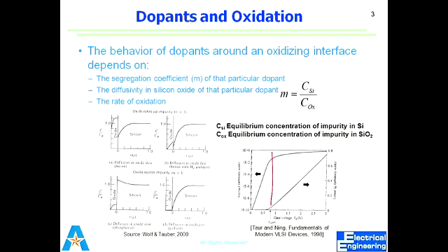As more and more oxide grows, it consumes a particular amount of silicon, because it's consuming silicon to grow the oxide layer. So a particular amount of silicon is consumed and a particular amount of oxide is added, and this is the total thickness now. So the silicon and silicon dioxide interface also changes, and the rate with which that interface is moving also contributes towards the redistribution.